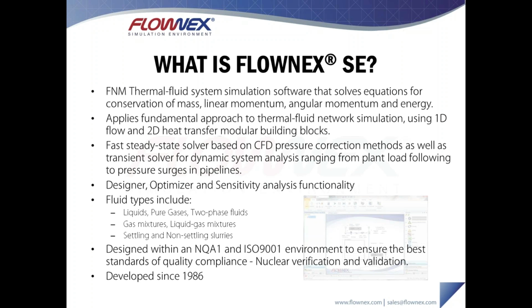The sensitivity analysis functionality is also quite useful in trying to better understand the system and understand the inputs. It can be configured in two ways. One using a parametric table where the user specifies different cases they would like to test, and the other one is using a Monte Carlo analysis where the user just selects a distribution function and Flownex generates random data and calculates results for that.